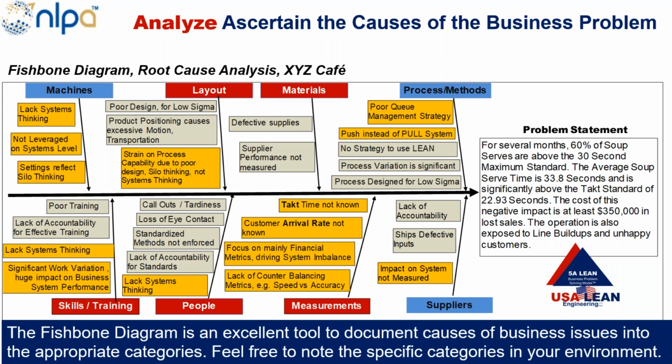And the takt rate is calculated by taking the net available time divided by the customer demand. So you have to understand customer demand and the net available time, and you'll come up with the takt time. Again, understanding time and how it impacts quality. This was a very critical case where time affected quality on different levels.